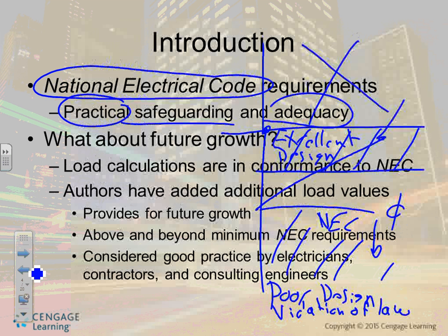You know, how do you overkill? Every receptacle right here, you bring a branch circuit to it. Are you crazy? You know how much money you're going to pay for that one? Now, if you put 4 or 5 of them in one circuit, good industry practice, versus 10. But if you put each one of them in one circuit, you have to justify it. How do you justify it, Jay?